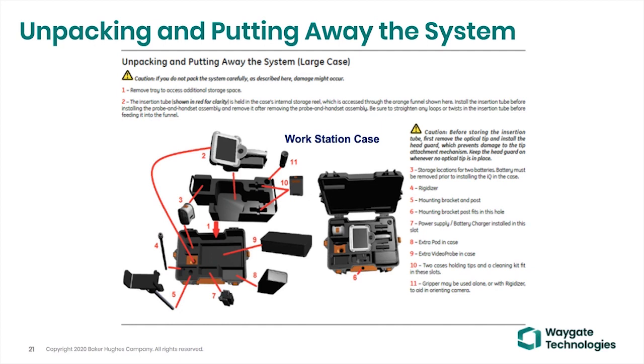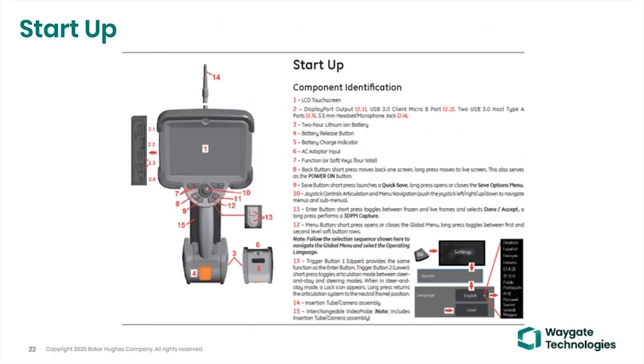Well, if an O-ring stays in compression, it gets hot, it gets cold, sits on the shelf for a few months, that O-ring is going to go into compression, and you're going to start seeing at some point an image that looks like it's milked out or has white. It's really an indication that even though the O-ring is installed, you have abused that O-ring by keeping it in compression and in storage and in hot-cold situations. So that's why you want to keep this head guard on the camera when you're using it or in storage.